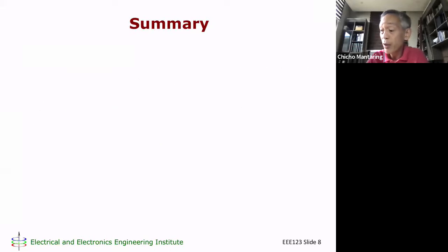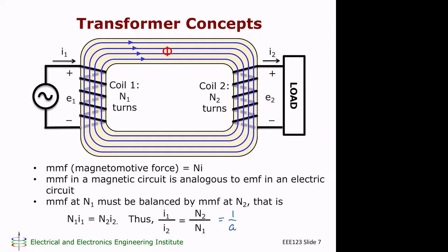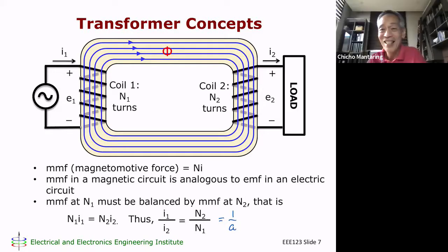Let's go back to this. The phase difference between E2 and I2 will depend on the load. For example, if your load is a pure inductance, what is the phase difference between E2 and I2? Can I hear an answer? Shout out lang. What if this is a pure inductance? Ano yung phase difference between E2 and I2? Nakalimutan na ninyo? Try to remember. Sir, 90. Exactly, 90 degrees, right?